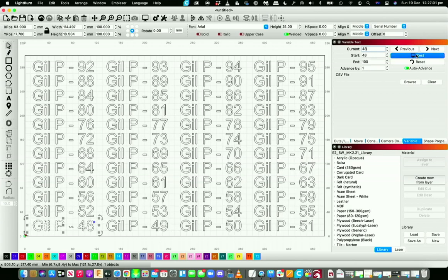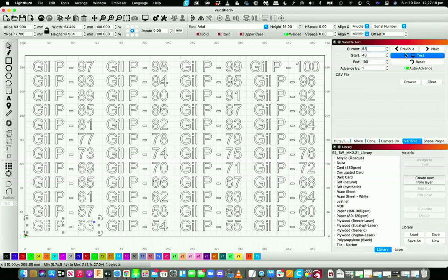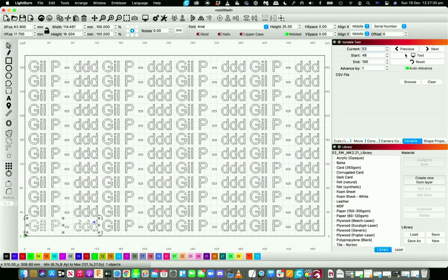So in this case, because the job hasn't finished, we can actually define where it goes. I started at 48, you've also got to tell that current number. You can actually change that. Maybe you've made a few cuts that have come up, the numbers are usable, but we come back and you can see 53 is exactly where that lower one picks up, the one that's highlighted right now. So you have quite a little bit of ability to change those options.